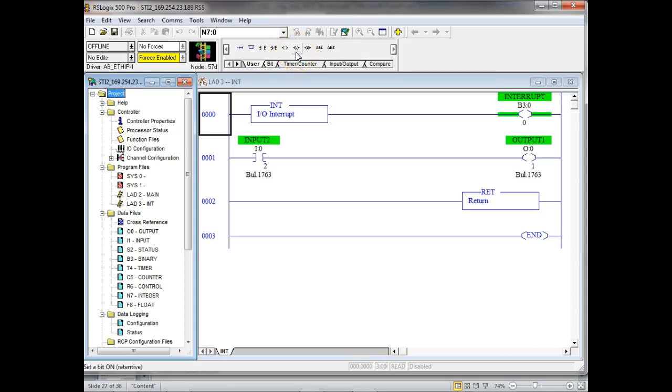Latch. So that's a retentive output, and reset. So these would not be disabled. If this was latched when you came in, inside the MCR, it would still be true, right? You understand that? Everybody okay? But it's not scanned, so it wouldn't be updated, right? Does that make sense? So a latch and an unlatch could be considered a critical output.